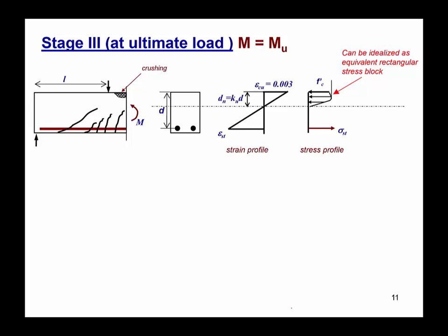As discussed earlier, if we integrate the volume under this stress curve, the stress profile in the concrete in compression, it gives us the total compressive force that is acting on the concrete. Now it's rather difficult to integrate the volume under the nonlinear curve here. So instead of integrating the volume under this nonlinear curve, we will simplify it, we will idealize the nonlinear true stress block with the equivalent rectangular stress block as shown here.